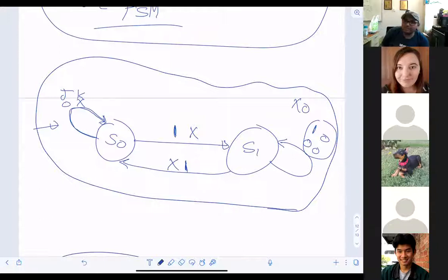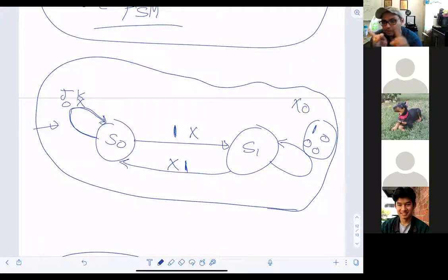So, let's summarize what we learned today. We started the whole discussion by reminding ourselves that the elements used for the sequential circuit are the SR latch, moving to the SR flip-flop, fixing the SR flip-flop, moving to the JK flip-flop, fixing the JK flip-flop, trimming into two different things, which are the transition flip-flop and the data flip-flops.